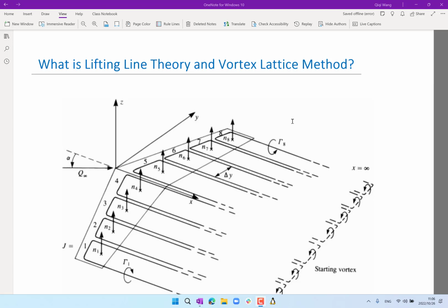And we know that the downwash essentially tilts the vector of lift. And from how much that vector of lift is tilted, we can calculate how much induced drag there is on this wing, right? So this kind of method is used not only analytically to calculate the induced drag.